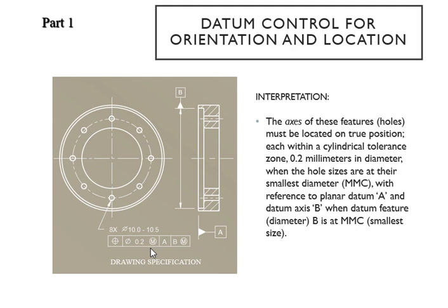And it is telling you your MMC is with secondary B, and the other one is your little hole right there. There's nothing for this datum A, which is your primary datum, and that's your drawing specification. Okay, you've got 8 of them, right? These little holes right there have to follow that. Okay, the hole is 0.2, that's your diameter for the circles.